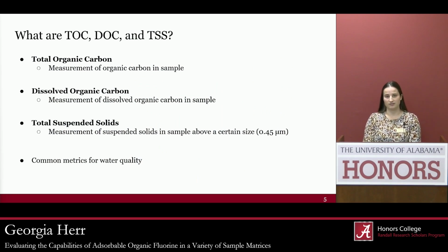First, I'll go over TOC, DOC, and TSS. TOC stands for total organic carbon, and this is a measurement of all of the organic carbon that is contained in a wastewater sample. DOC is a subset of this carbon, and it is dissolved in the water, which means that it is more difficult to remove with filtration processes.